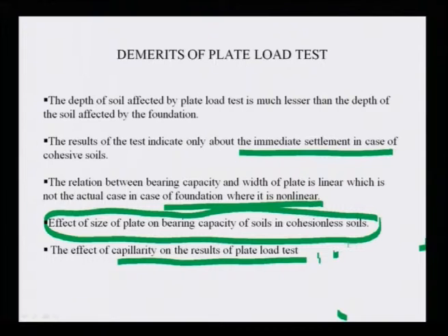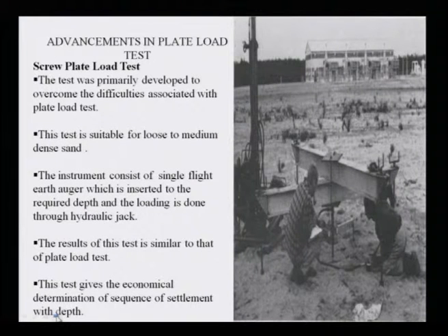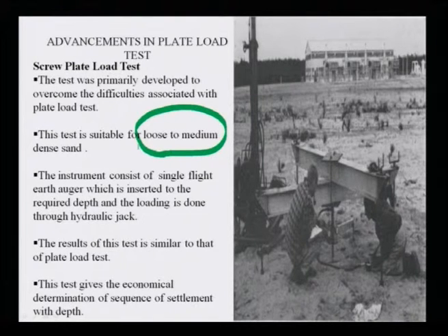These are all limitations. There is another test, called the screw plate load test. This test was primarily developed to overcome the difficulties associated with the plate load test. The test is suitable for loose to medium dense soil.